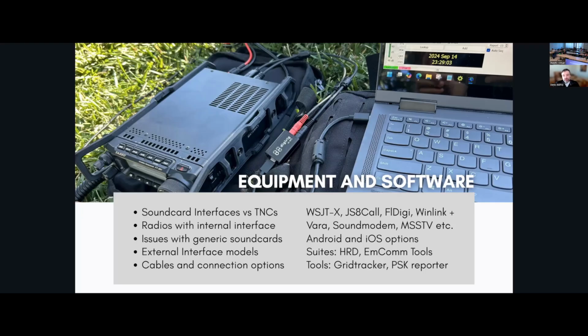The difference is, with the sound card based digital interfaces, the encoding happens in the software on the computer, and you can change the encoding schemes by just switching between different software. So although TNCs have their benefits in terms of very little setup, the sound card based interfaces like Digirig have the benefit of flexibility: you can run any audio-based encodings on it and just switch the software as you need to move from one to another.